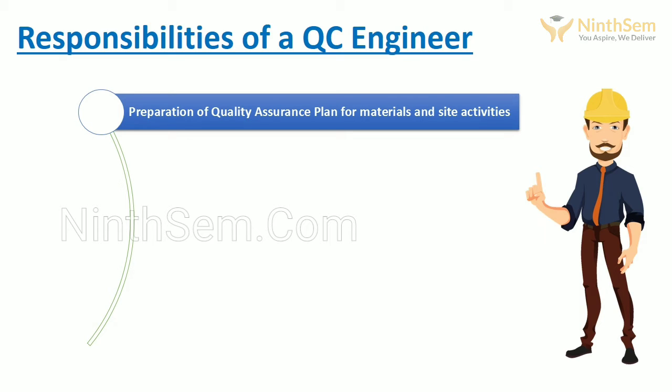Like the materials, various construction stages are also required to undergo testing before the items are accepted and payments to the contractor released. QAP for activities includes preparation of method statements, job safety, environmental analysis, and checklists based on specifications of the project.